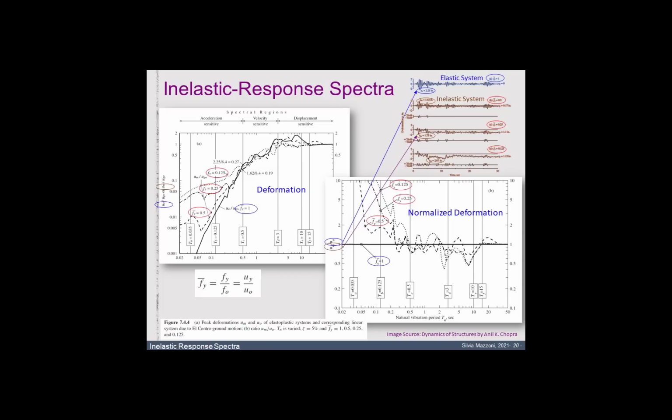You've got your model, and this is from Chopra's book, therefore this is a simple elastic perfectly plastic system. So we've only really added one additional parameter, which is your yield strength. And now you can really see that by just changing one parameter, we get very different responses. The difference in responses really depends on the period of your structure. And you can plot different quantities, and it's very important to think about what quantities and what type of response spectra you want to look at.